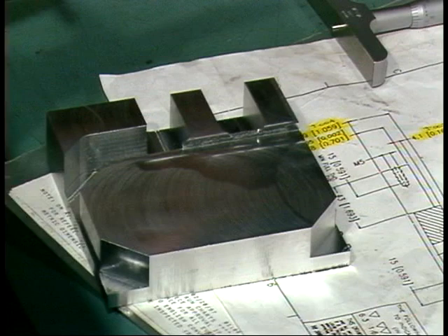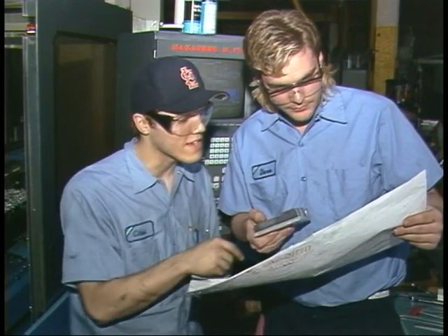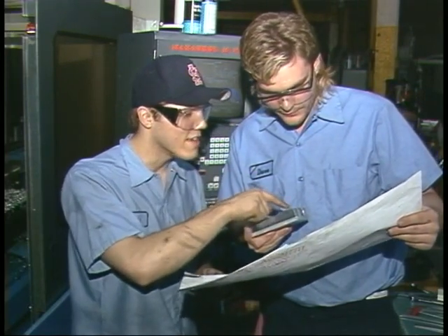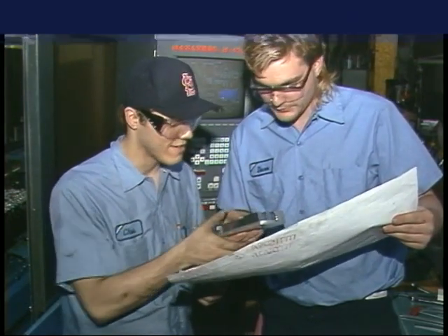For example, if the nominal size of a feature on the print says it should be 10 millimeters and 55 hundredths, you should be able to look at the feature and determine if it is close to the whole millimeter and that there are no large discrepancies. If the feature looks like it is only 5 millimeters or 20 millimeters, you will be able to visually identify the discrepancy and realize that this is a problem.